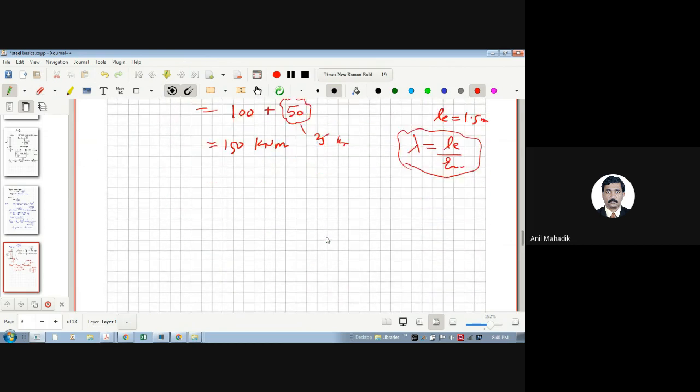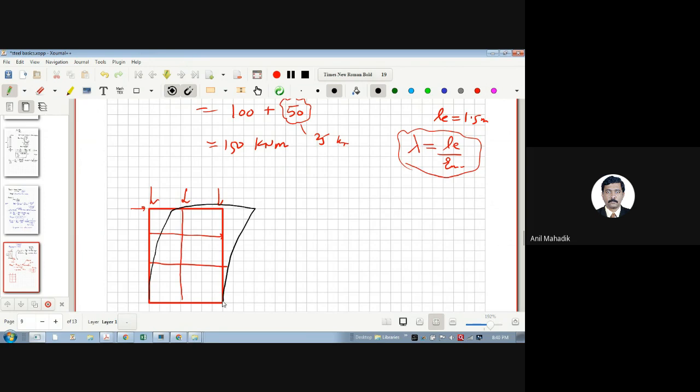See, generally in whatever real structures there are, there is a possibility of buckling due to vertical loads. There are vertical loads in the building, and there may be lateral loads. Then the building gets a sway like this. Building is having sway. With vertical load there is also a little sway. So if the force is shifting here, there will be P into e. So there is a moment due to